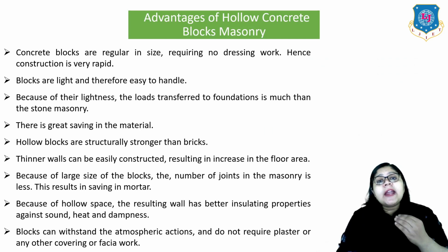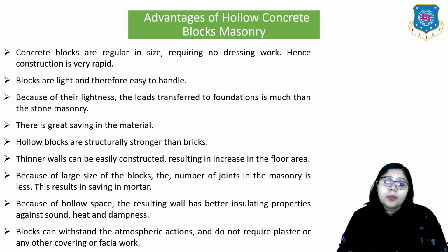Now there are some of the advantages of this hollow concrete block masonry. The concrete blocks are regular in size, requiring no dressing work, hence the construction is very rapid. Blocks are light and therefore easy to handle. Because of their lightness, the load transferred to the foundation is much less than with stone masonry. There is great saving in the material.